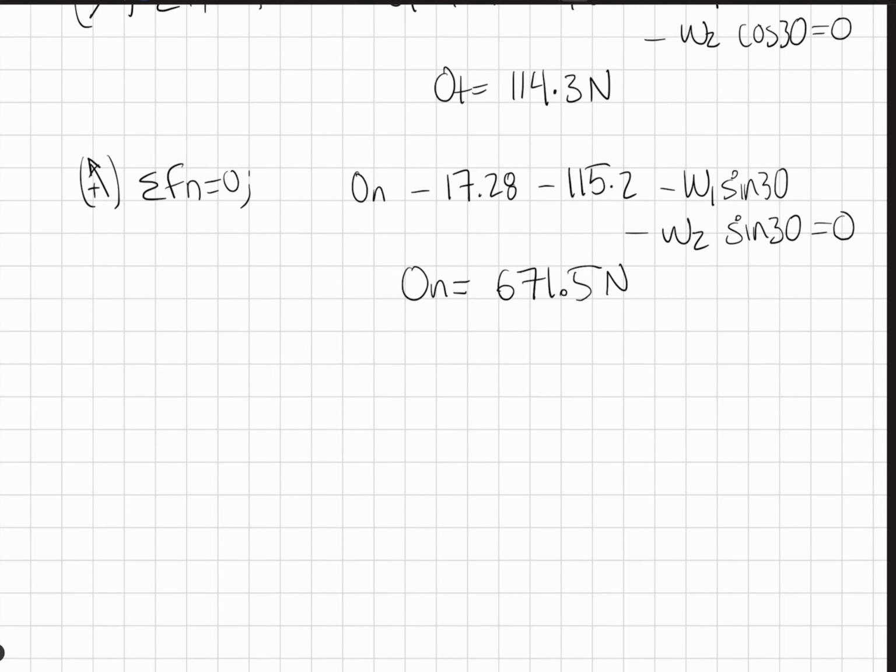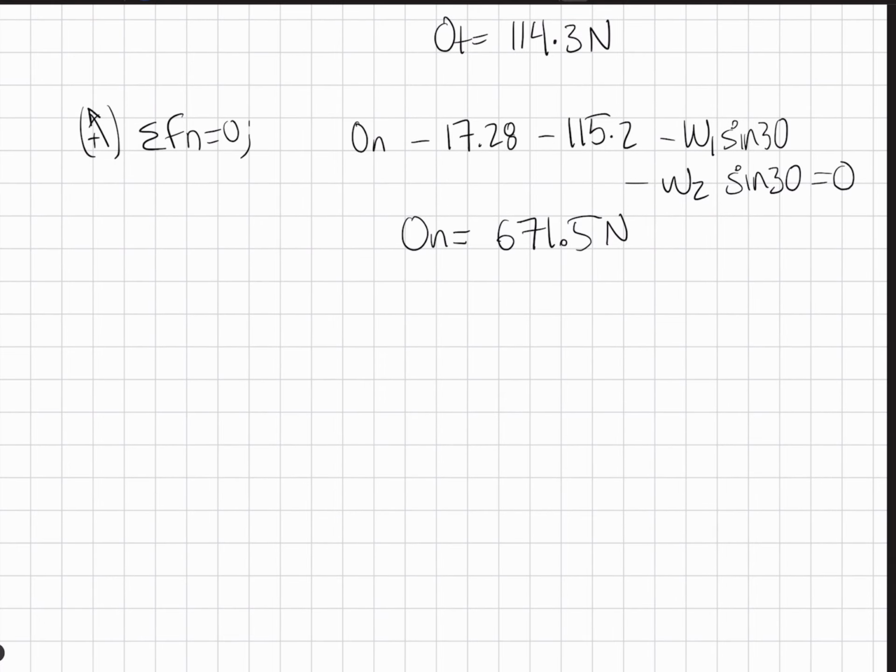And of course, because we're looking at forces in two different directions, in the tangential and normal directions, we could always sum them together using the square root law. So this is generally how we go about doing so. And this gives us a sum of reaction forces as 681.2 newtons.